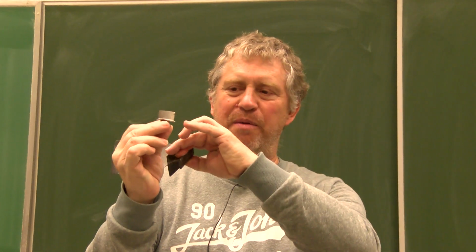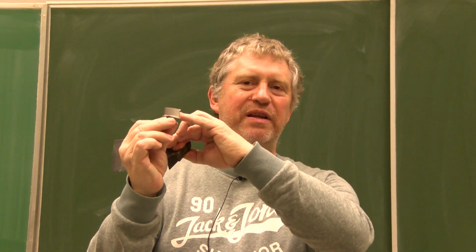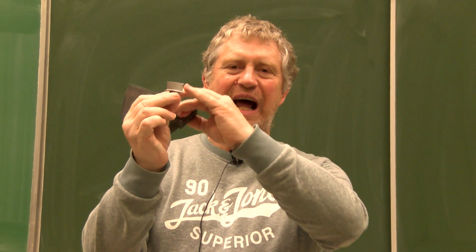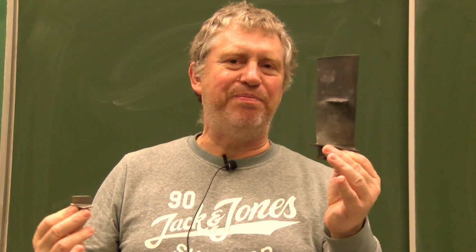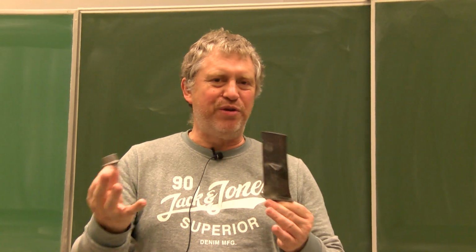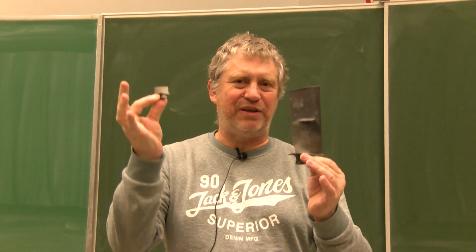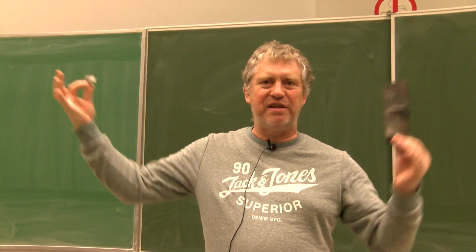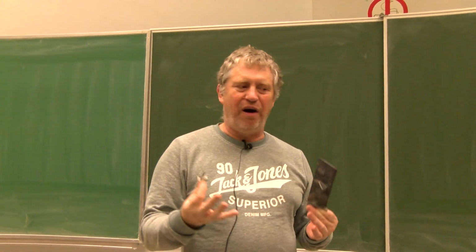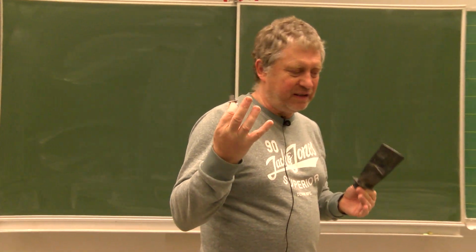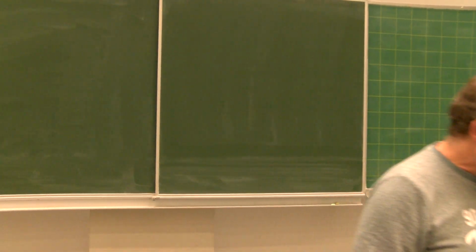When you have a problem over, let's say, 0.5 centimeters, 5 millimeters here, this is half of the blade. Here, 5 millimeters, this is 10% or 5% of the blade. So you understand that the situation is not at all the same if you are in the final stages or in the first stages for the same degradation of, let's say, the leading edge or a part of the blade. This is very, very clear.